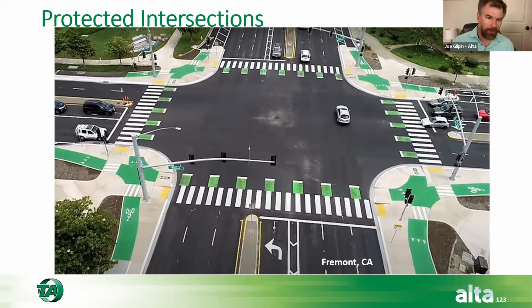Yeah, so Jessica has a comment. It helps that their streets are ginormous, but they didn't reduce their travel lanes in most cases here. What they did was, you can see the old channelized right turn, the old curb line on the side here. I always forget that you can't see my mouse on the other monitor. So here's the old right. So they're requiring a slower right turn at the corner in doing that. So I'll show you some examples of other types of intersections here too that are smaller in some cases.